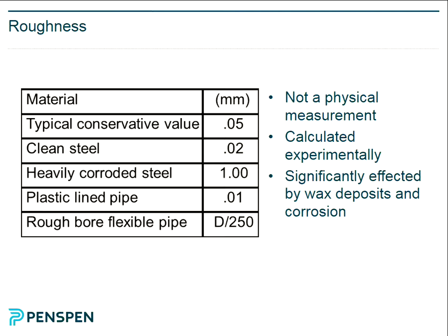So the advantages: high capacity, very efficient. Low delta pressure. If you compare it with multi-phase flow, you've got a relatively low pressure drop. It avoids uncertainties. With multi-phase flow, you've got lots of uncertainties. You've got wax, hydrates. You've got liquids being produced. You've got the uncertainty of the calculation. You've got all these complex multi-phase flow equations to worry about. So it avoids all of that stuff.